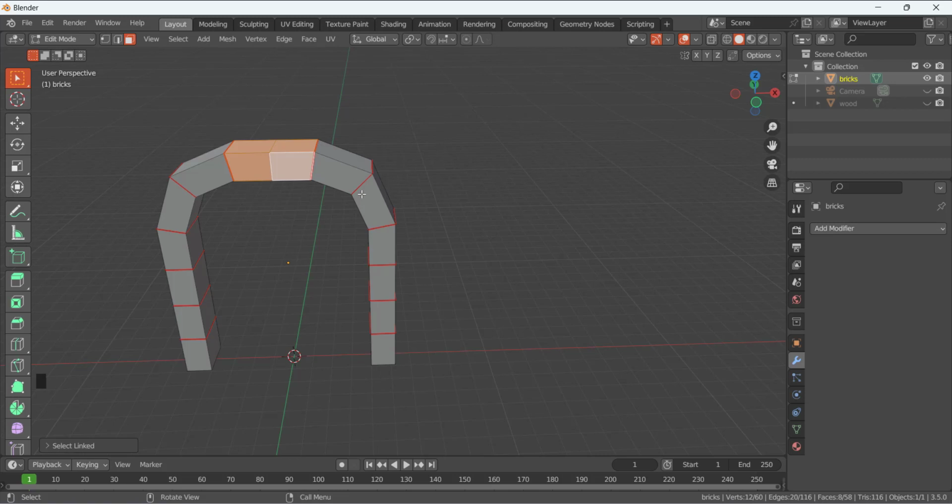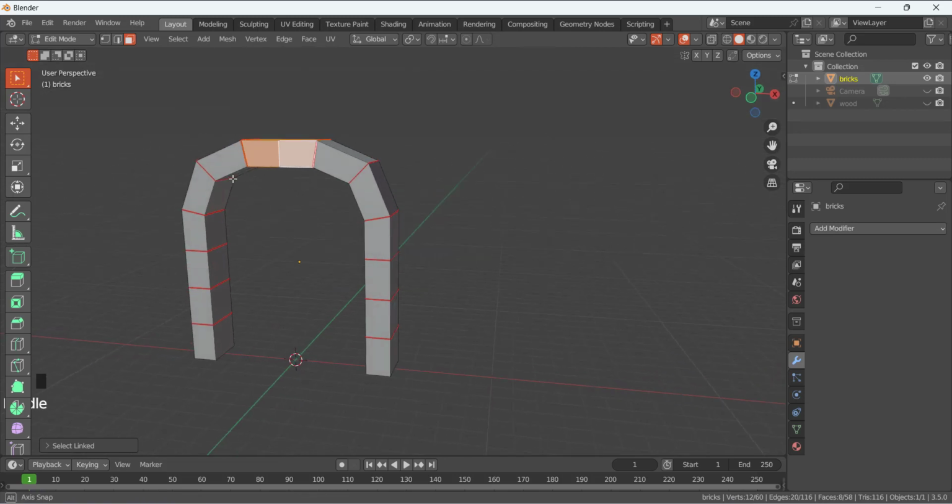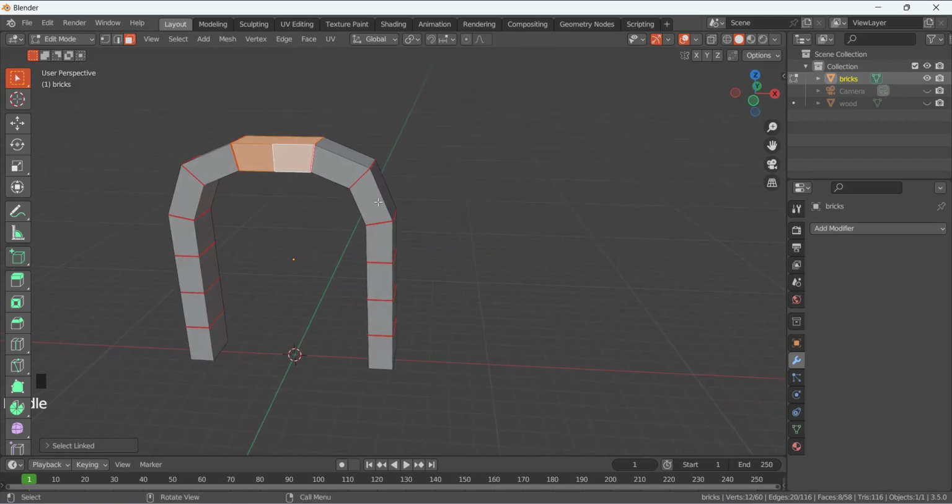The seam is added here, like a wall. So basically it's separating the object from it, but these are connected. Okay, so we just select this one and leave this one, press move to this face and press L, and the same way, leave one and select the other.